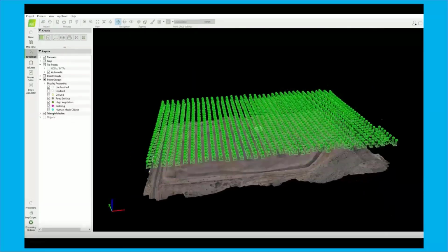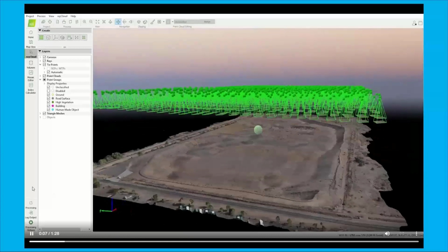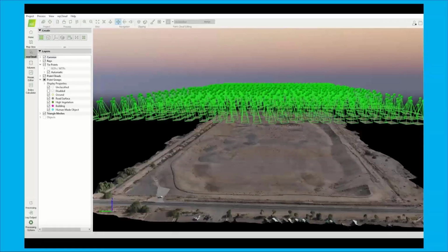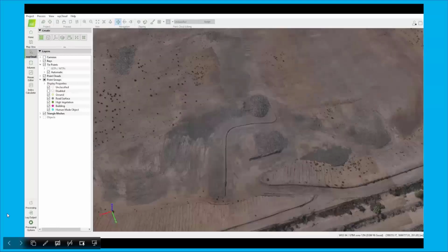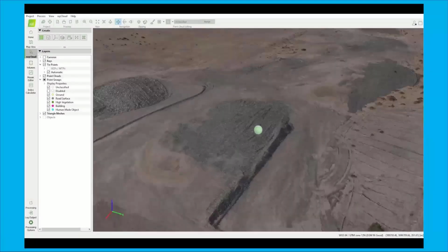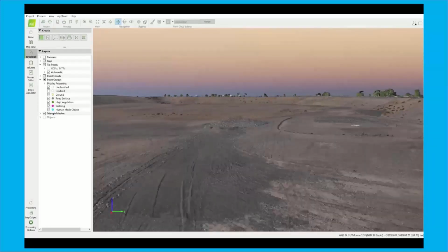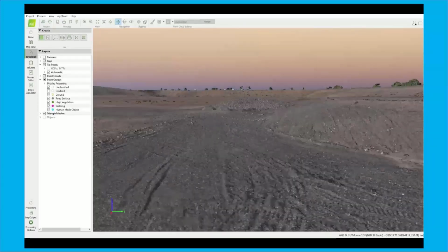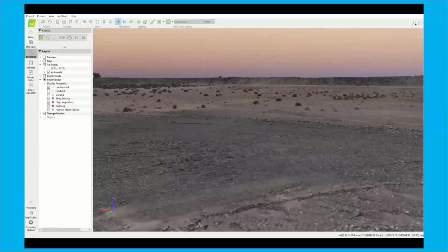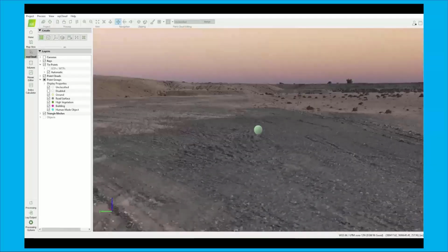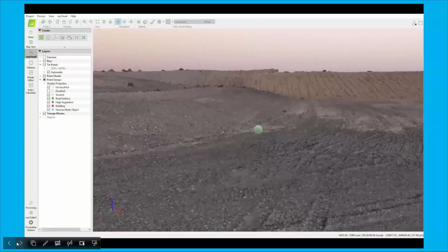And then one big tip and trick that I wish I had at my disposal, or I knew about it, which I was trained on, so I should have, but I completely forgot, is setting the flight into a crosswind. So we talk about the tolerance for winds on our aircraft being 20 miles an hour, gusts up to 25. Well, that's terrific. But what if we set it up into a pure tailwind? Now we have a 70 mile an hour ground speed. That's tough for the camera to keep up. So we typically set all of our flights for grids into a crosswind.